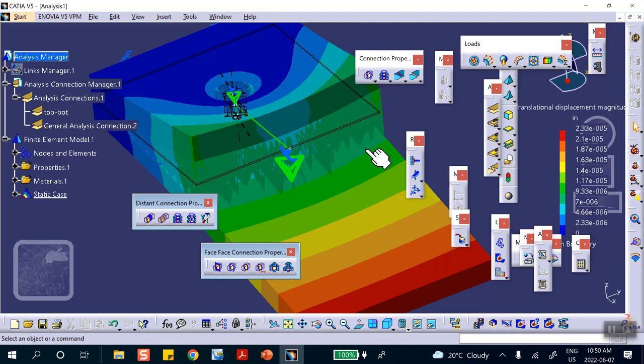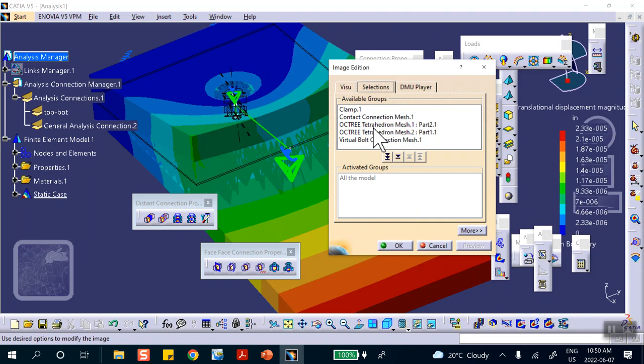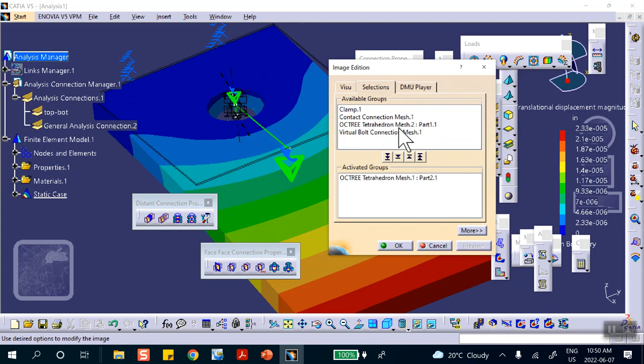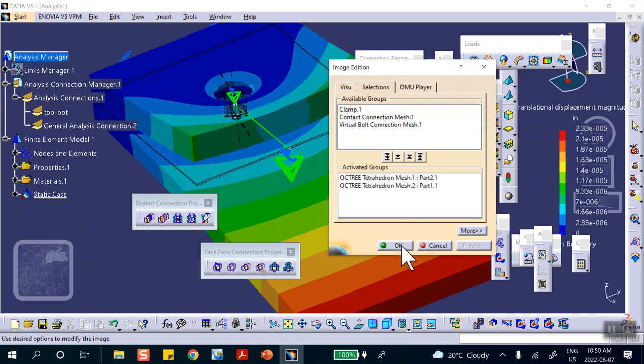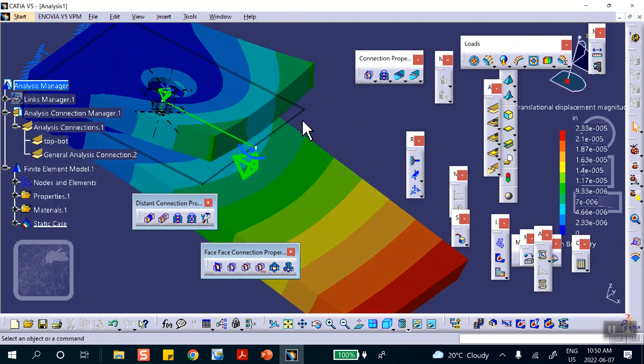And if you don't want to see this garbage in the middle here, double click. Don't show me all that, those internal elements. Important elements, but I don't use them. Internally it's used. So just show me the mesh that I created and this one, and there is no bolt. And then you can put the load if you want at the end. It makes no difference. So that's the story behind virtual bolts and bolts. Of course, bolts are more accurate, but it may not be feasible.